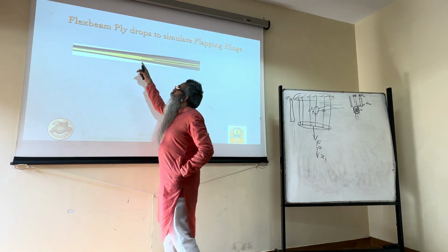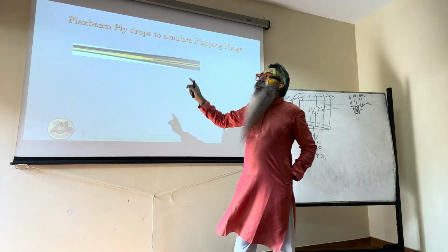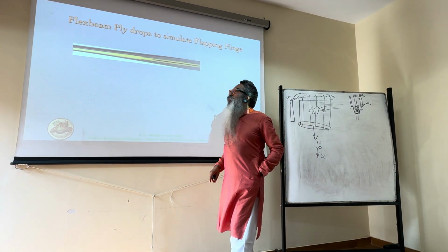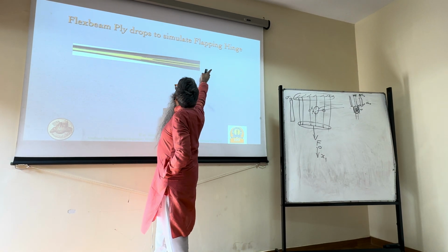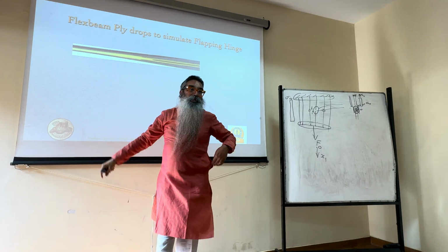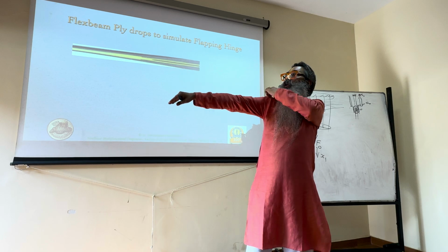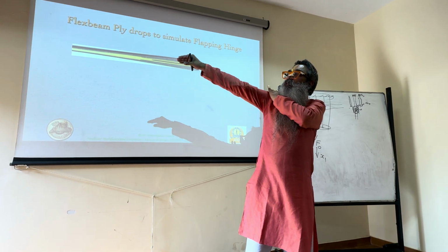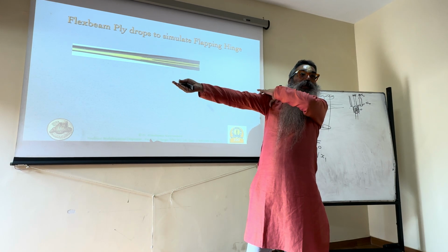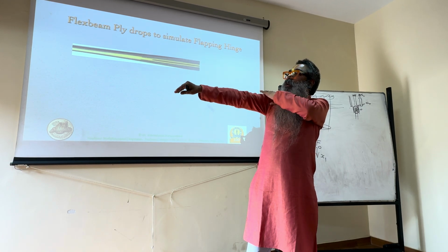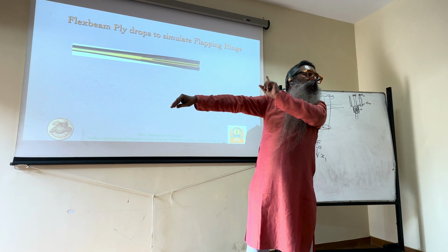Now if you look at it, it's a hybrid kind of a structure. The lighter yellow colored ones that you see are glass fiber epoxy composites. The dark black colored ones that you see are carbon fiber epoxy composites. So this is just a section view of that. You see that over the length you want to drop off the plies, because as I said earlier, helicopters were fully articulated. They had a hinge in this direction, they had one more hinge in this direction. This is called the flapping hinge, lead lag hinge, and then there is a bearing called the torsional bearing or the pitch bearing. Now most of today's helicopters, modern helicopters, have done away with those two hinges and bearing.